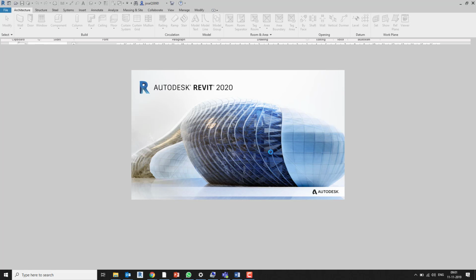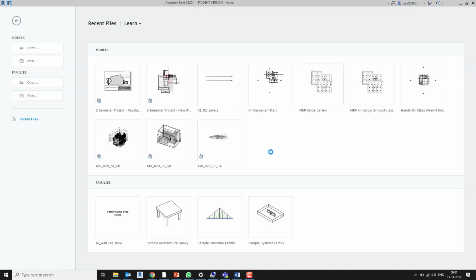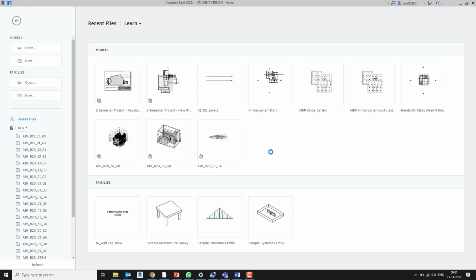Does it make sense if we do this number? Because otherwise it wouldn't be right. If we put minus 1,000 for this, it doesn't really represent the truth because we have lots of concrete on top. No, but wouldn't it be more like minus 600 or minus 500? Yeah, I think so. It depends on how much concrete you have, because the concrete is going to consume a little bit of your wood. But if the wood is two thirds or even more, 3/4, something like that, yeah, 2/3. So 2/3, yeah, I would say 600.